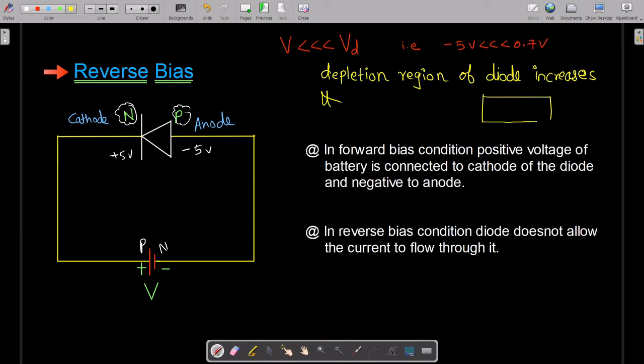See, this is your diode, this is that particular junction, and this particular junction increases. So let's suppose this was your junction, let me erase this. Since you had connected this diode in reverse bias, the depletion layer is going to increase somewhat like this, by decreasing the P type. So let's suppose this is your P type and this is your N type. Earlier your N type was up till here and your P type was up till here, but now due to reverse bias, you have connected this diode in reverse bias condition, that means you are giving negative potential over here, and you are providing positive potential on this particular side.